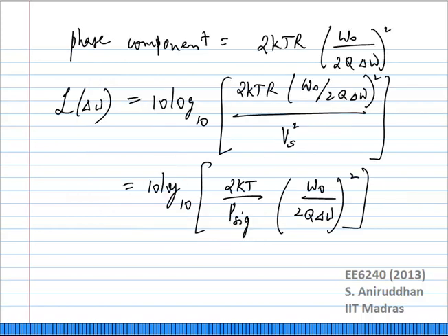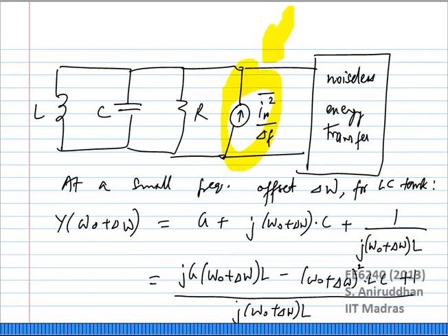the frequency response of the tank at omega naught. Remember, this is not just at any frequency. We are talking about the frequency response of the tank around omega naught. If I build a 4 gigahertz oscillator, but I have flicker noise only up till 100 megahertz, does it mean that I would never see a 1 over f cubed region?